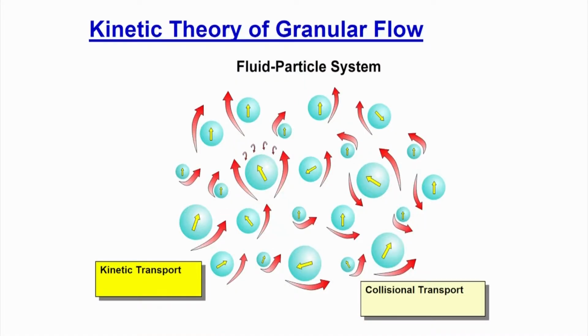And Euler can be used for the plastic regime and viscous regime. Now, what I said is that in the viscous regime, particularly, most of the fluidized beds come under the viscous regime. What we need is a kinetic theory of granular flow to model the collision, to model the flow actually, because the flow depends on the kinetic theory of granular flow.